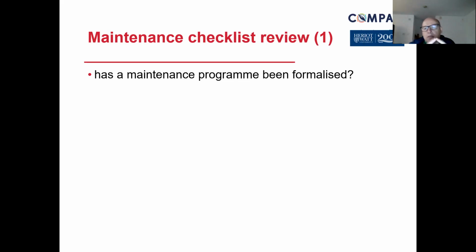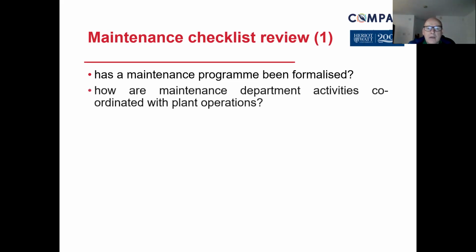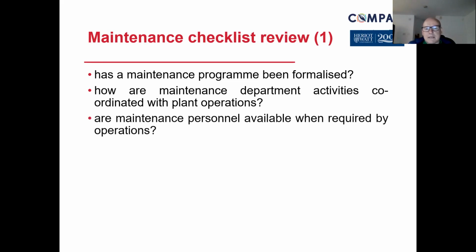So bear that in mind in terms of the competent person doing checks and what's actually needed on the checklist, because if you only view what's on the checklist, you're only getting part of the overall picture. Longevity might be that you've not looked at one part for 3, 4, or 5 years, and that could be safety critical. So it looks at the program and formalizes it. It looks at the maintenance department and what they do and what they don't do in the plant operations, and what's needed from a reactive and how you can be more proactive.